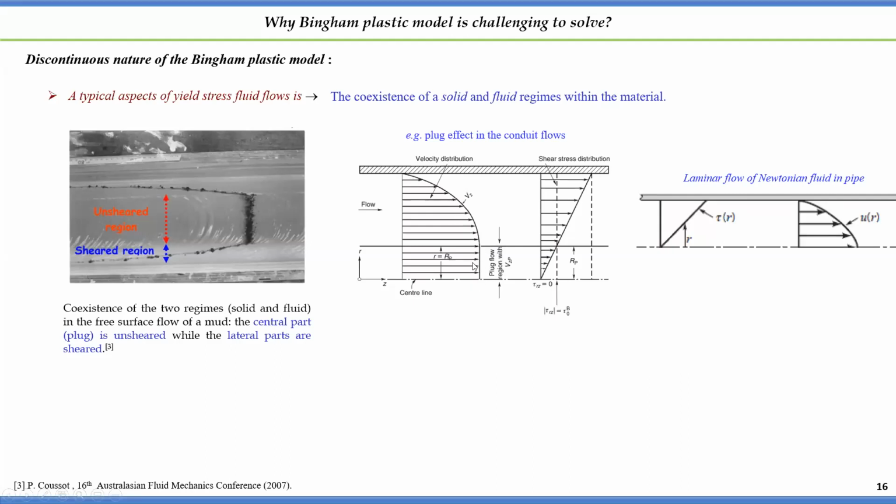So what is the meaning of this velocity profile? Let me explain. In this central region, your fluid is moving, and all the elements of the fluid move with constant velocity. You are not able to see a layer moving above another layer with some different velocity. They are moving with the same velocity.